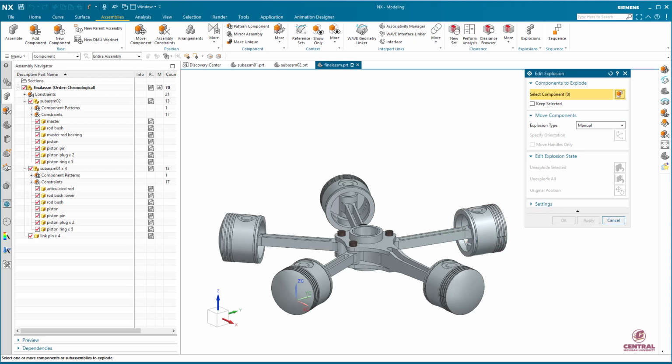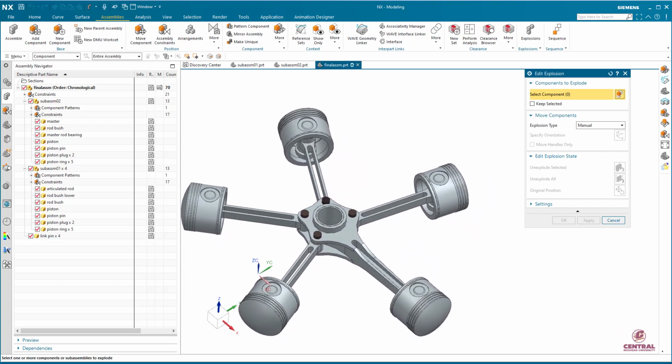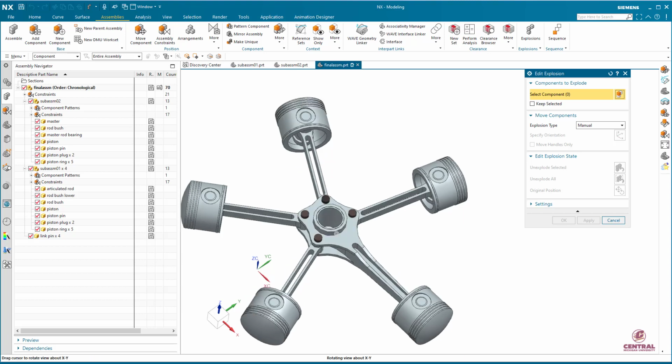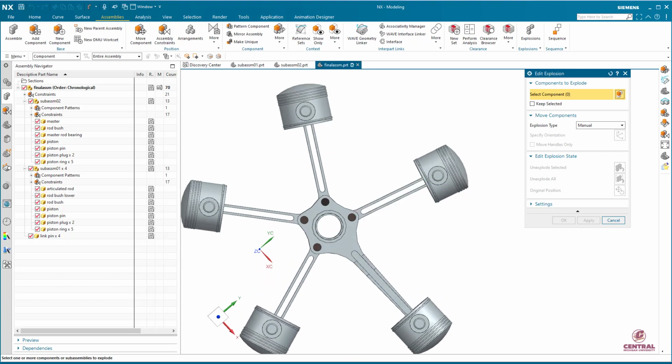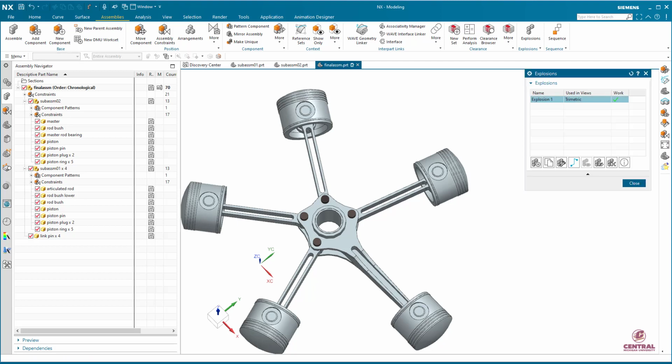Then you can start moving the part you want to move. So in this case, I want to move this whole thing, including this sub-assembly itself, out. But when I move it out, I want to make sure it follows the direction of the angle I already have. So I'm going to choose only one of these. But when I try to click one by one, as you can see, it chooses only one component. But I want this sub-assembly to move. So you got the idea, right?